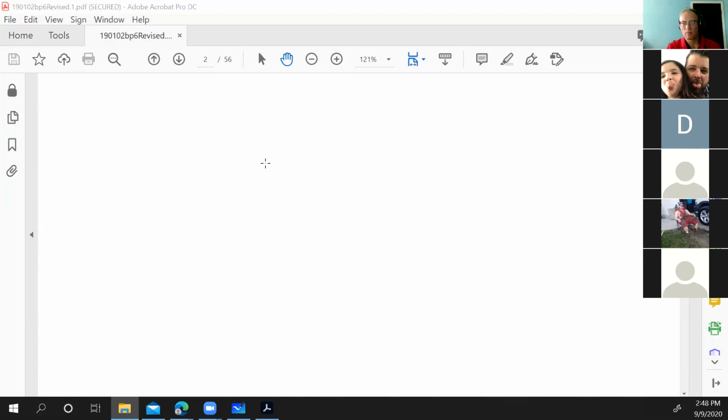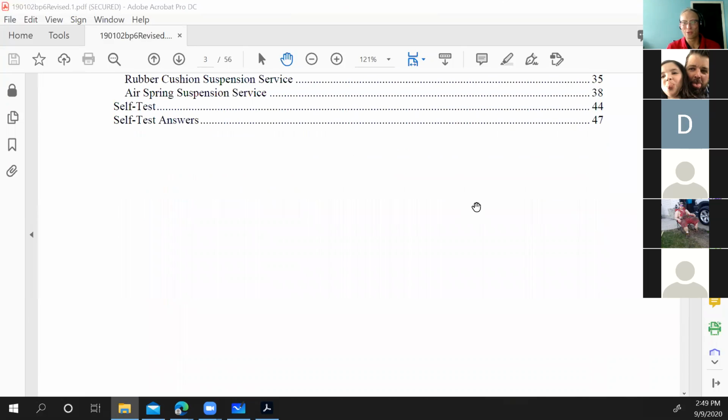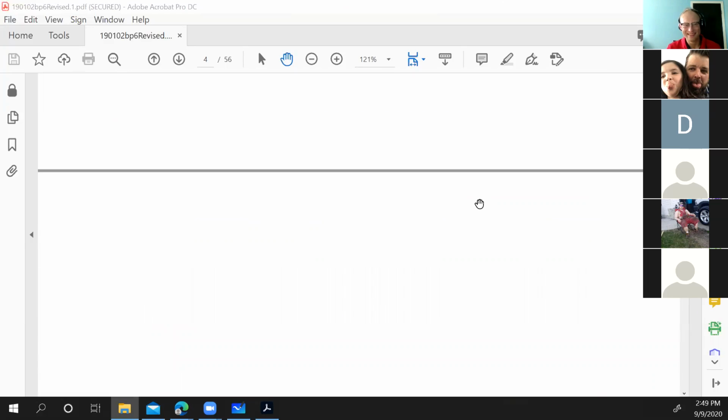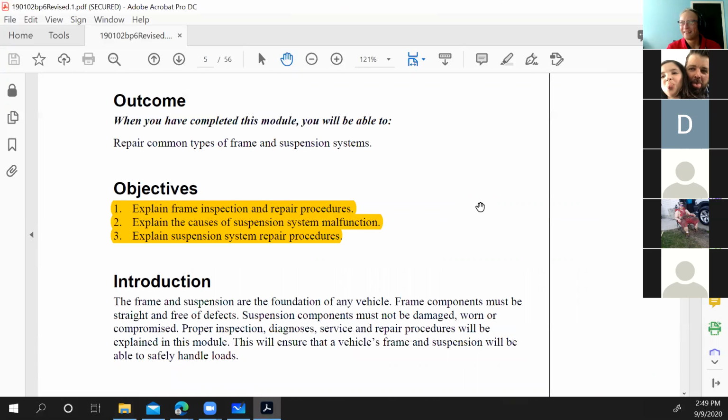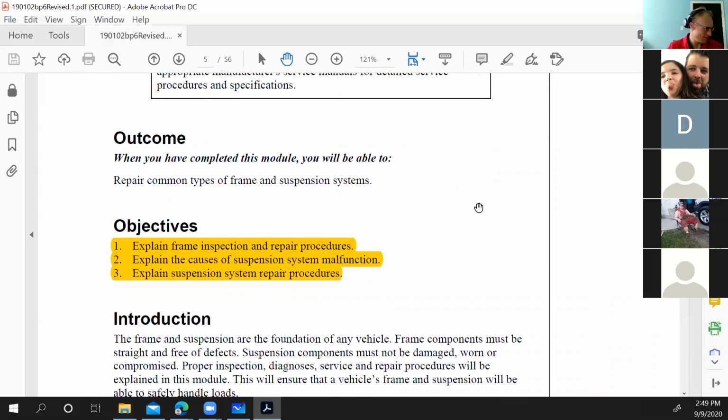Do not drill holes in the flange of the frame. It seems like you've already read this, or you know one or two things about frames. I did it on my first day. You drilled a hole in a flange? I sure did. Put a bolt in it, you'll be fine. That was a learning experience, I bet. Yeah, do not drill a hole in the flange, ever.